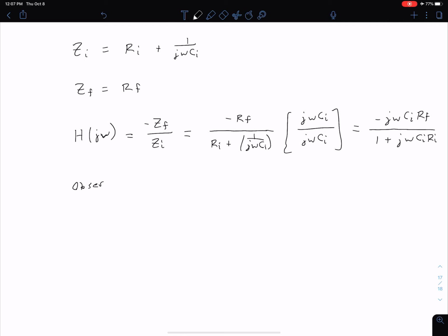We can either go back and compare to some of the general forms we saw for our first order filters with our passive filters, or we could go through doing our extreme cases again. So let's just verbally, without writing down, look at this briefly. If our omega is 0, we're going to have 0 divided by 1 plus 0, so that's going to be a 0.